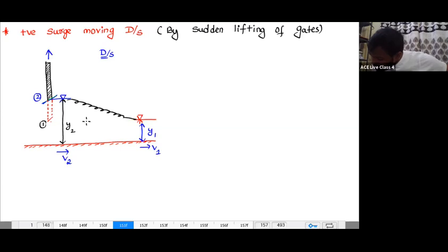So, up to this point, whatever this is, you see, this is a small elementary wave, or not? Yes or no? Elementary waves means small waves. Small waves are going to travel, and this is known as a surge, my dear. Here it is going to be the surge. And while it is moving, this surge is going to have a velocity known as the velocity of a surge wave.